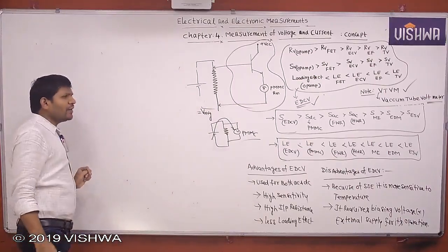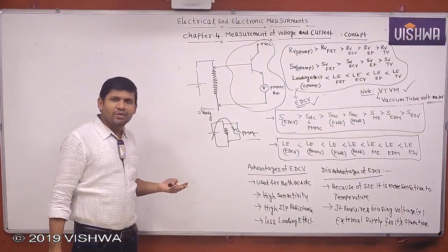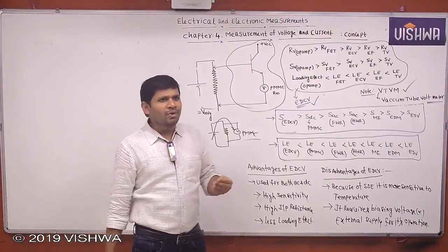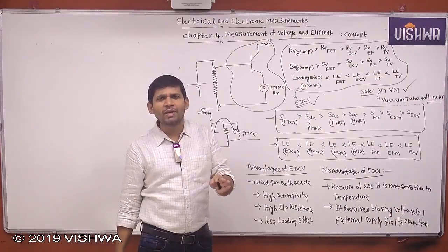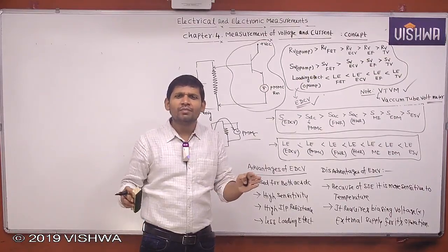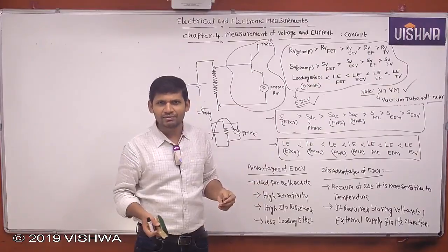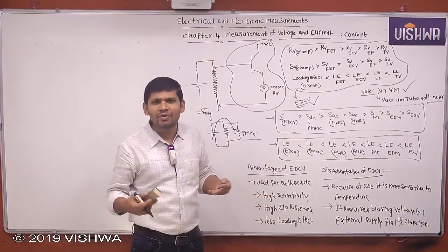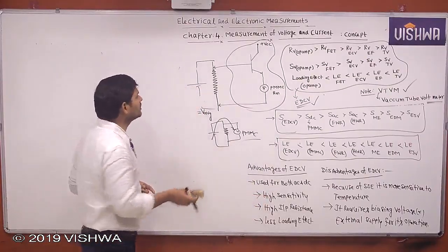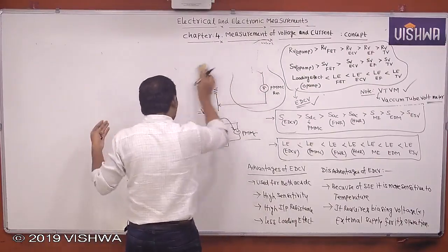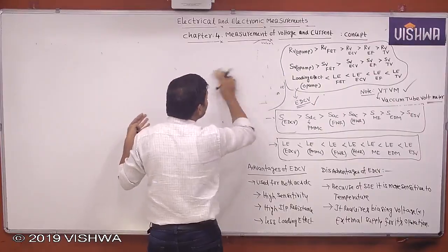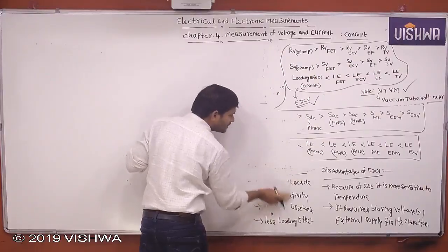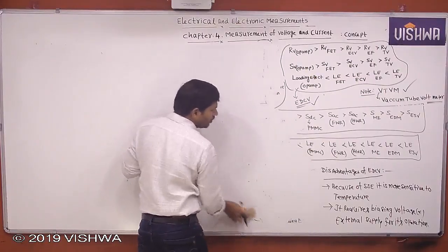See, not only amplifier type instruments, practically we are also using amplifier-rectifier type instruments and rectifier-amplifier type instruments. These are all milliampere and microampere ammeters. In order to measure milliamperes and microamperes, you can mainly use this type of meter. That is, if you want to measure very low currents or low voltages, mainly low voltages, we can use these voltmeters. To sense very small currents also, we can use these meters.